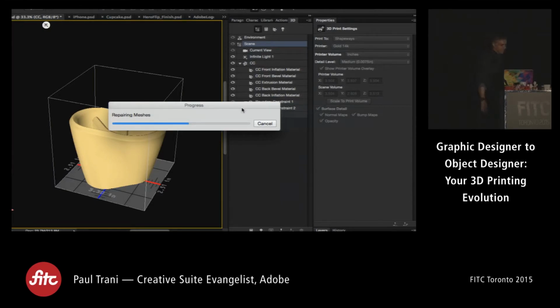All right. I'm tempted to cancel out of this, but what I'm going to show you is you're not going to see that scaffolding, right? Because what does Shapeways and Sculpteo use? They use those big industrial printers where everything is a powder. So it doesn't need those supports, because if you're, again, printing me in my hand, it doesn't have to build up that support because it's all in powder. The powder supports it. So there's nothing to break. There's no cleanup that needs to happen.